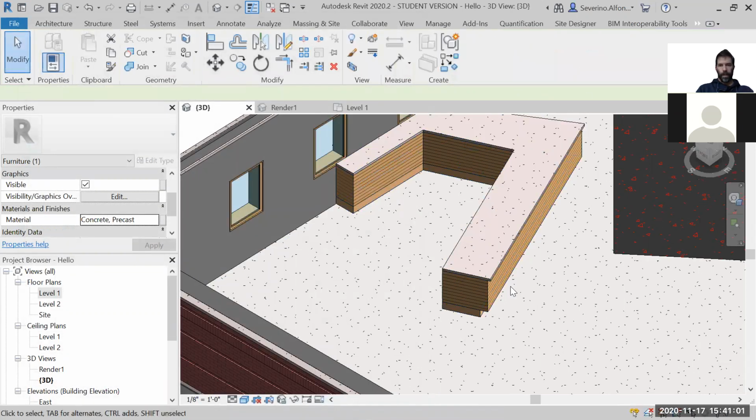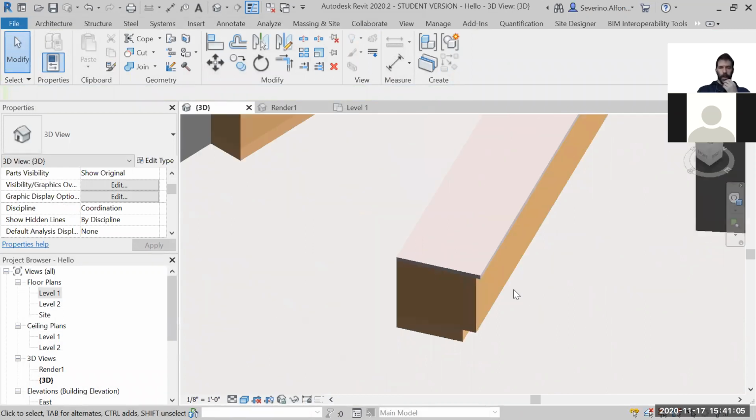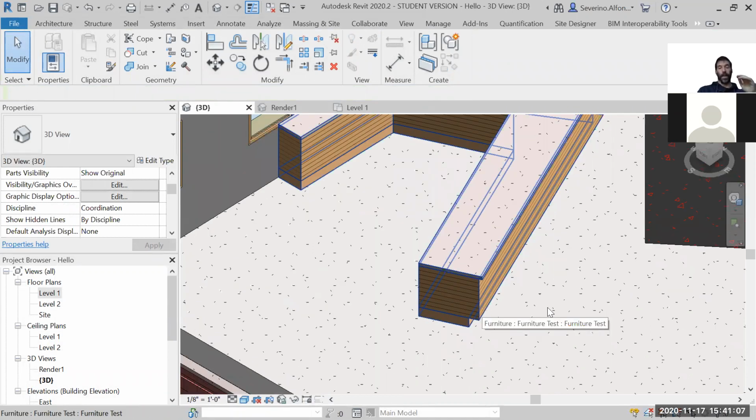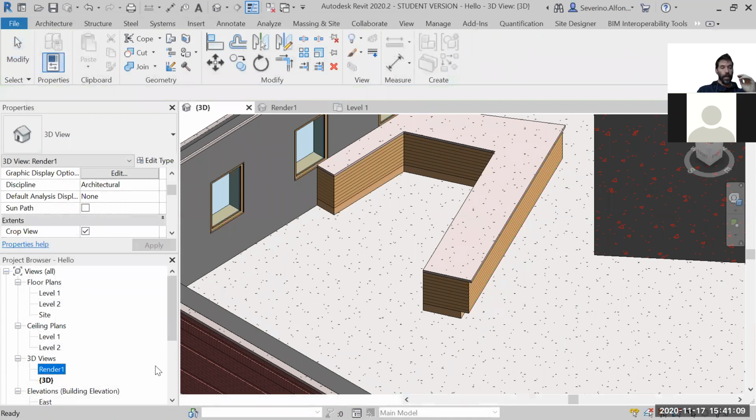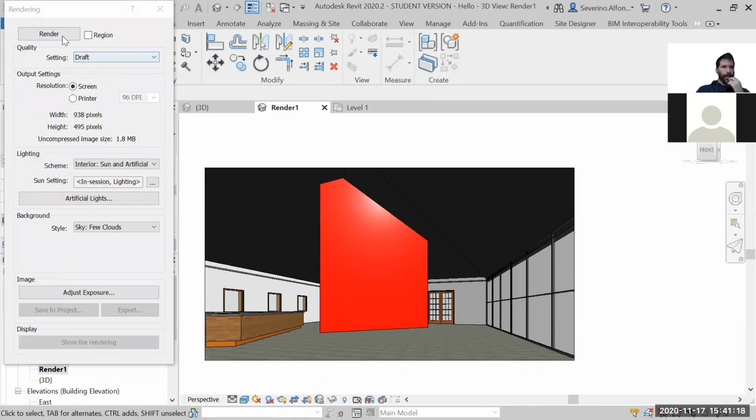So notice that by just shifting a couple of sets of extrusion, this is one single model with 3 extrusions inside. Okay, so now I can go to the rendering, and there you have this little nice thing that you can easily render. You can do, by the way, render region. I don't know if you have talked about it, but you can just select the portion of the render if you don't want to render the whole thing.